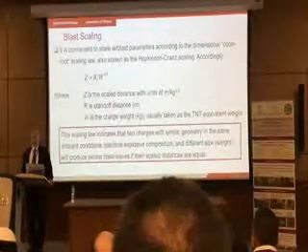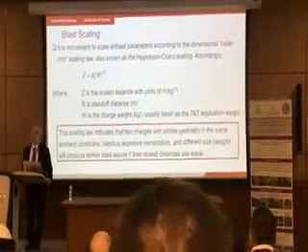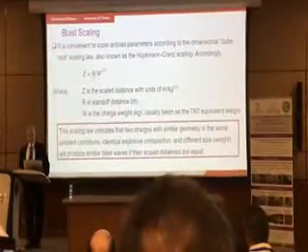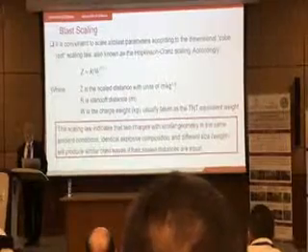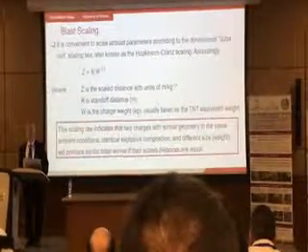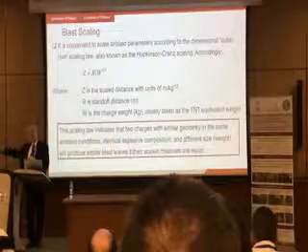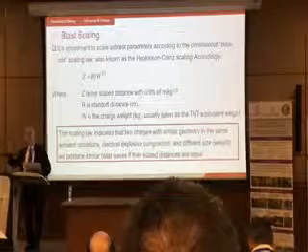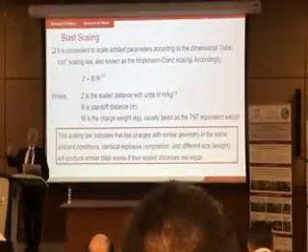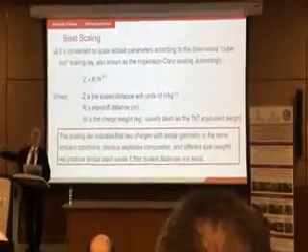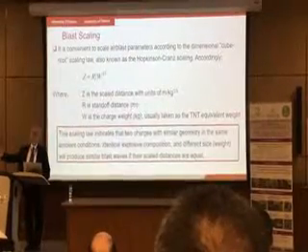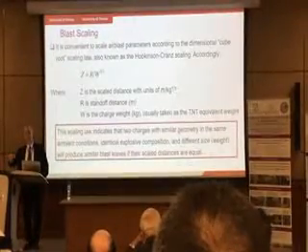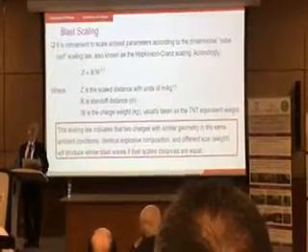But Hopkinson-Cranz scaling law says that scale distance, Z, relates to standoff distance and charge weight through this equation, which means if I increase standoff distance by a factor of 2, I have to increase charge weight by cube to get the same effect. So as you can see, only increasing standoff distance from 10 meters to 20 meters, now I have to increase charge weight cube of the first charge weight to get the same damage. So this is very important.